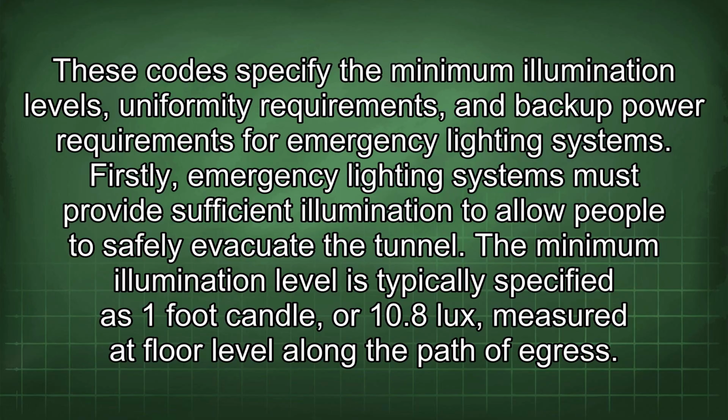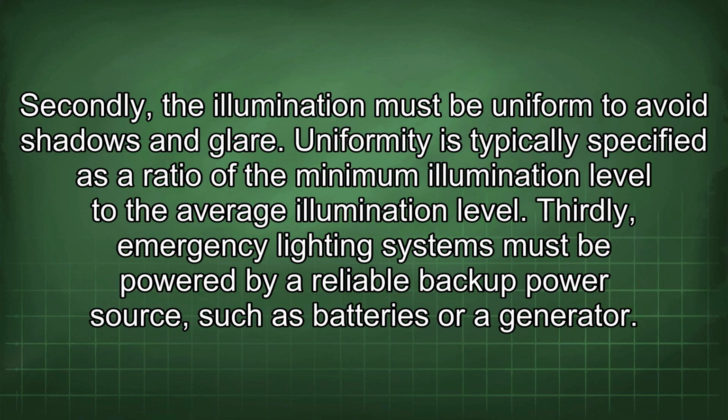Firstly, emergency lighting systems must provide sufficient illumination to allow people to safely evacuate the tunnel. The minimum illumination level is typically specified as 1-foot candle, or 10.8 lux, measured at floor level along the path of egress. Secondly, the illumination must be uniform to avoid shadows and glare.